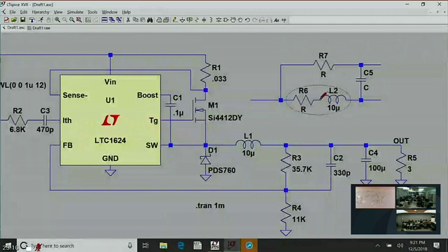That's the way it works. You have to know what the ESR of the inductor is and then pick these two. And if they're not matched that accurately, the whole thing actually still works too. It's a great technique. But anyway, we won't worry about that.